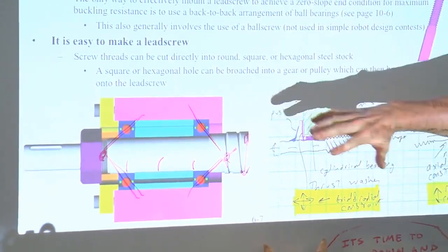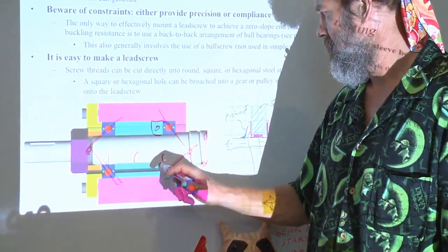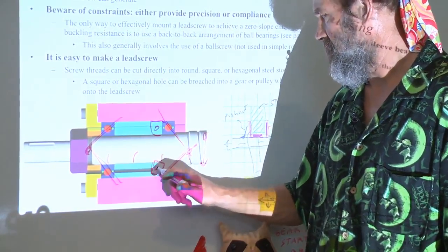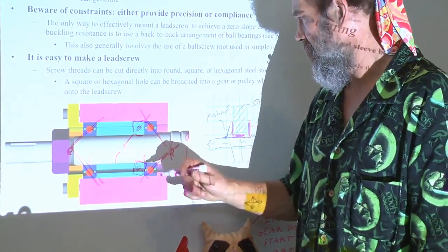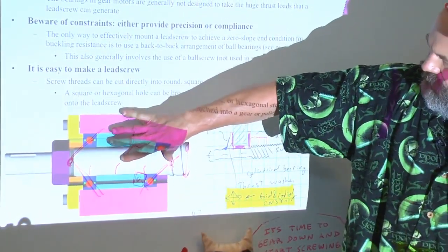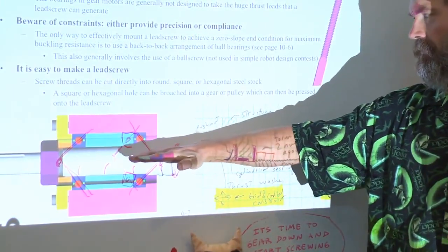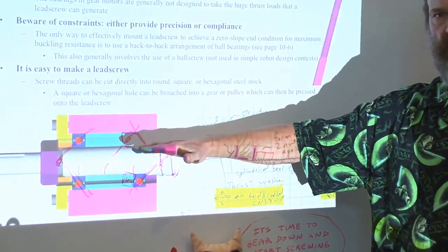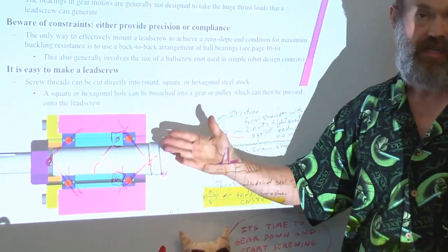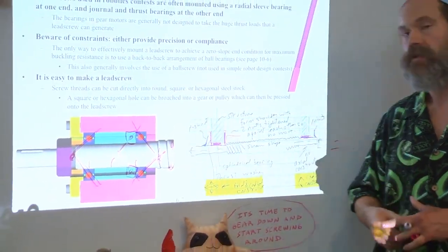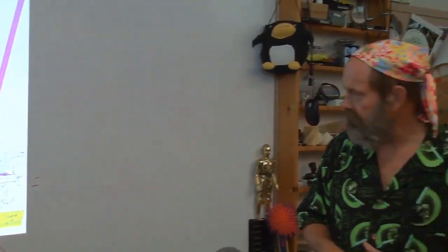It is perfectly rigid. If we had brought this bearing as a mount like that, which is often how you buy these mounts, you may have about 2 shaft diameters held. That's about halfway. It's not quite exactly rigidly mounted or fixed mount, but on the other hand, it's not simply supported. It's halfway in between. So you will want to make the assessment.